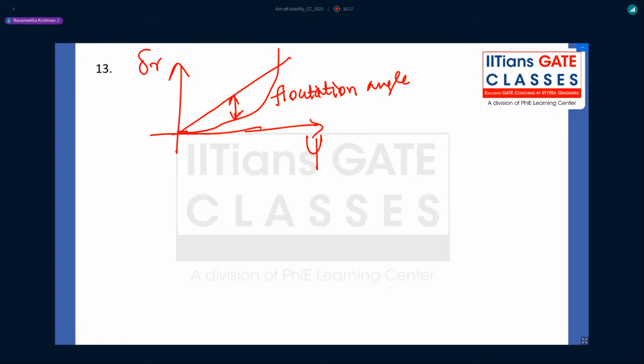This is the required rudder force to be produced by the pilot. The pilot has to supply that force in order to deflect the control surface. This corresponding position is called rudder lock. At very high angles of side slip, the floating angle will catch up with the required angle, at which the pedal force must be 0. Here the floating angle and the required rudder angle coincide. That means the required rudder force is 0.